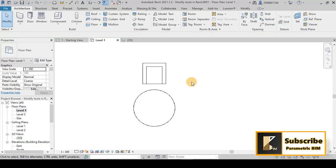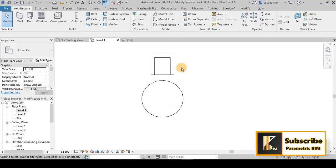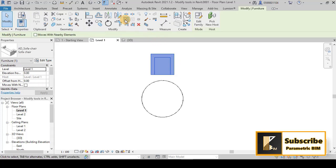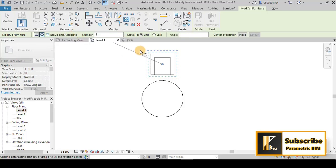Maybe I want to make 4 seats along this table, so I can use the radial array. So I will go here and choose the radial array, and then as you see I have here the center point.